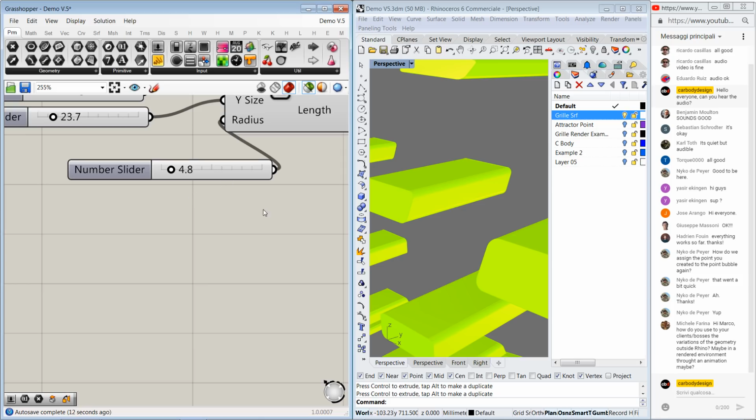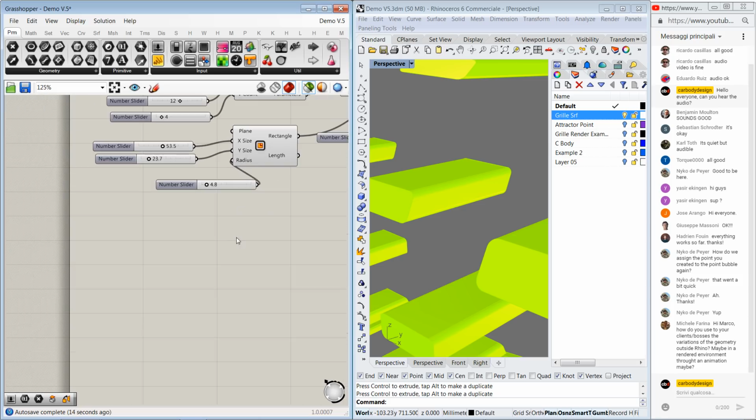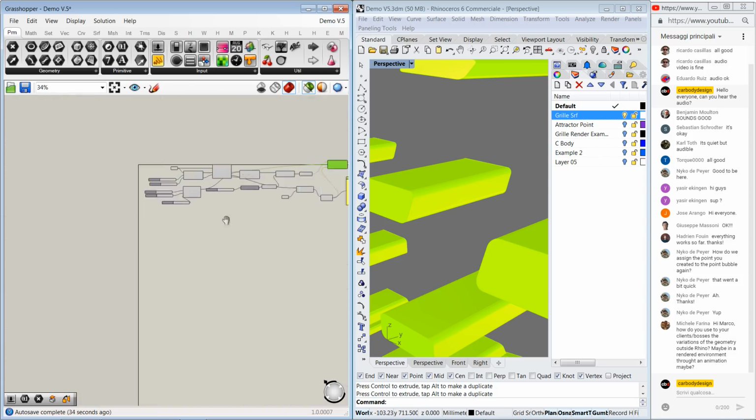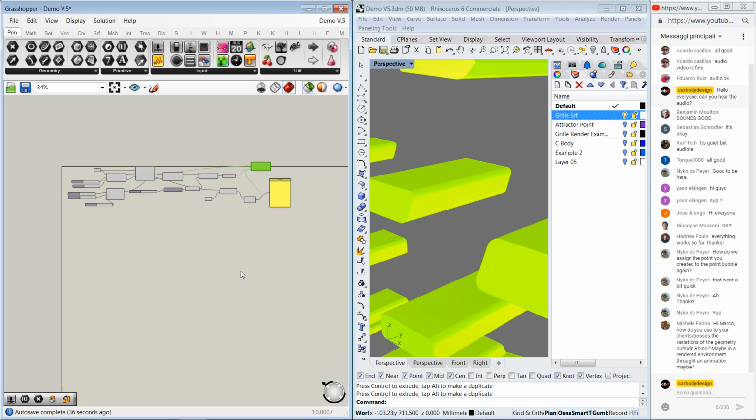So this means that we are able to implement some interesting features by adopting a correct workflow. In this case, we had to create these fillets on the profile curves and not on the final solid. So if we want to have this very fast response here, we need to have something that can be calculated very, very fast. Okay, I think the direction is clear.